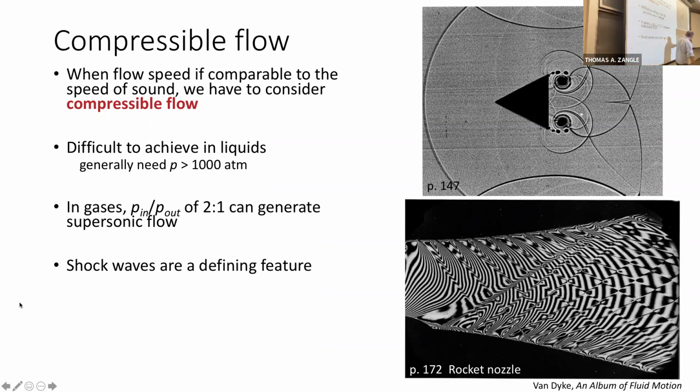So shock waves, which you see visualized here, we're going to see a lot of visualizations of shock waves coming from an album of Fluid Motion here. Shock waves are often a defining feature, not always, but often a defining feature of compressible flow. So when we do have supersonic flow, as in the velocity of the flow is greater than the speed of sound, then we will often get shock waves.